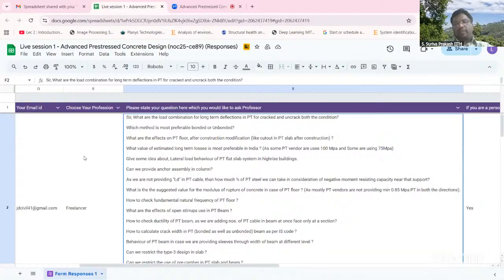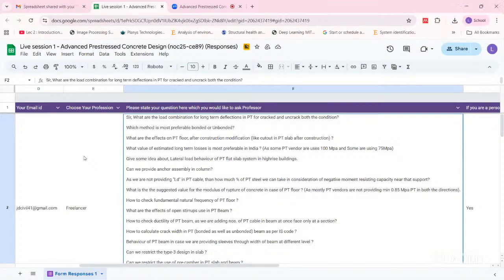You see, I think typically when we do strengthening applications, we take the anchors from the columns only, right? The major problem why we try to avoid providing an anchor assembly in the column in new construction is congestion of the reinforcement. Placing the longitudinal bar plays a major role in a column, right? Because it is going to help in both bending as well as in combination of bending and compression.